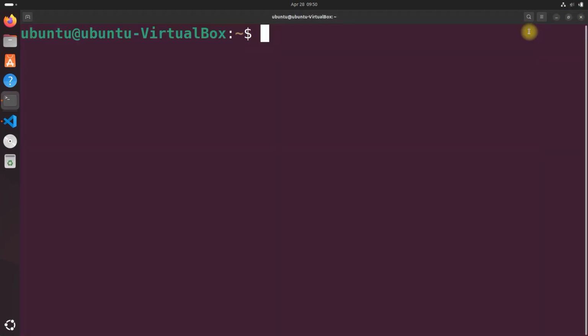All right. So that's what you typically do. You would pull the URDF from GitHub, from the manufacturer's repository, and then you'd bring those into your own package. And I did it manually rather than copying them over, but you can just as easily copy the files over into the appropriate files. I like to do it one by one just to have a look at each before I put them into my own package.